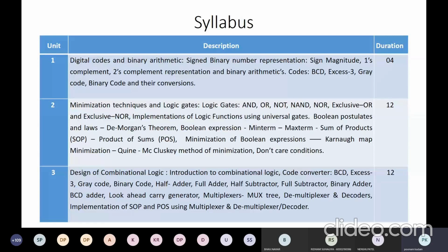Okay. Of course, the first part you will also simulate, and in addition to that, you have to do the second part also. Okay. I think it is clear. Similarly, let's take one more example. I'll explain how to design a full adder circuit using half adders. The same concept you have to apply to design a full subtractor circuit using half subtractors.